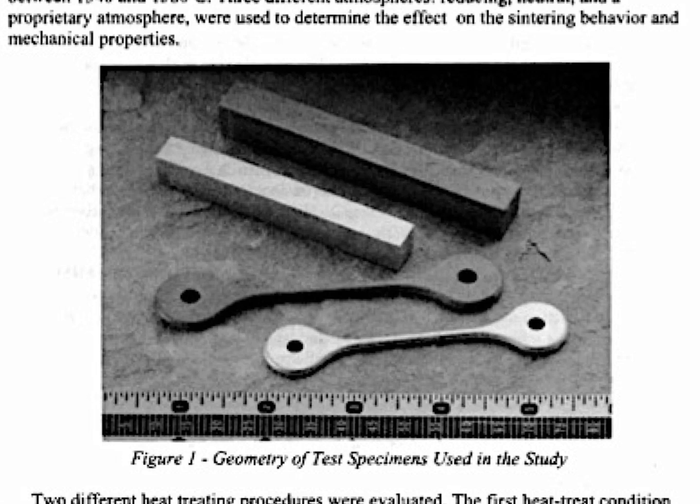So it comes out of the mold looking exactly like what you want it to be. Now, these guys are just doing some 4-point bend and tensile testing, but if we're making a part that goes into a human, this is also the goal. All right, injection molded, sintered, full density, right properties, right shape, with very little machining. Of course, again, as I keep saying, femoral heads are bright, shiny, smooth, so obviously we have to machine for that, but at least you don't have to grind away a block to make a sphere. All right, so that's your motivation right there.